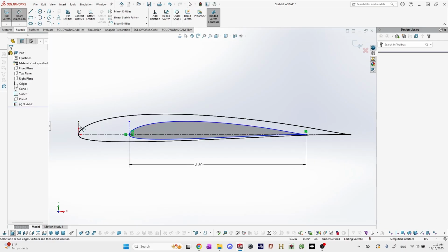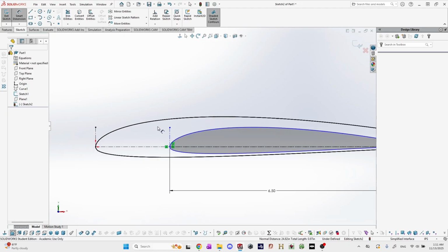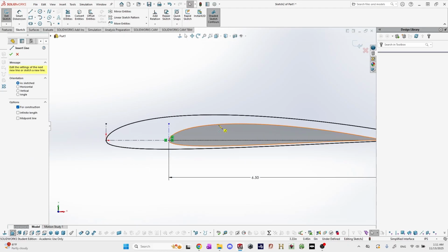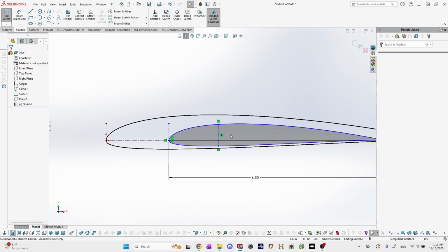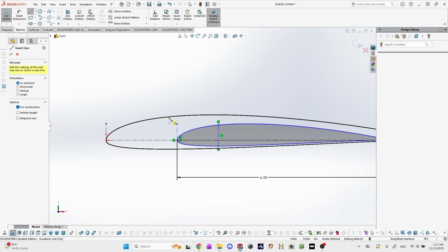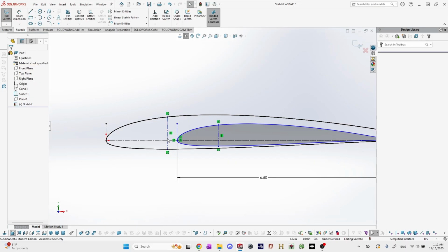There's either just mathematically setting the distance between these two and figuring out what that is, or we can actually draw the quarter chords. So I'll do that just because that can help if you don't want to do the math. But yeah, I'm going to draw a vertical line. Make sure this is vertical. Vertical line on my tip airfoil, and then another one of these construction lines on my root,